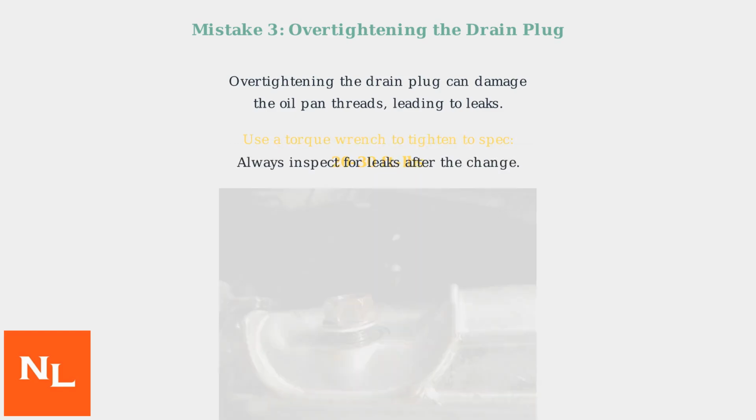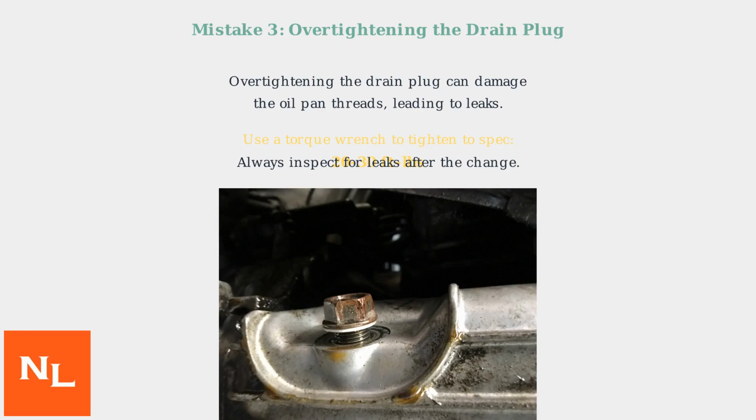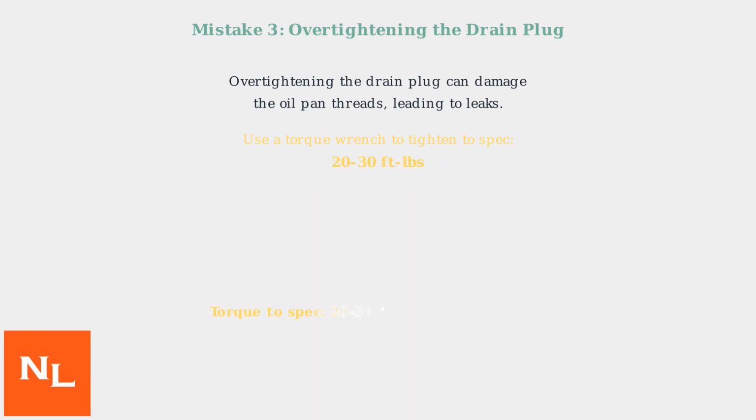Finally, after tightening, inspect the area for any signs of leakage. Look for oil stains around the drain plug area. Remember, proper torquing to specification prevents damage and ensures a leak-free oil change.